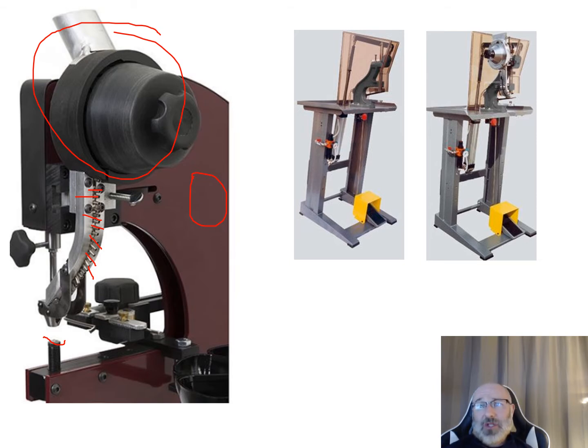Now, as we get to some heavier duty rivets, this might not give you the force you need, especially if you're working with a stainless steel rivet or something like that, where it's not quite as ductile a material, and it's going to need a lot more force to round it over in order to achieve that shape that you need. Even if it's just over a washer or if it's not, you're still going to need quite a bit of force for some different types of rivets, especially as you move into the tubular and semi-tubular rivets.